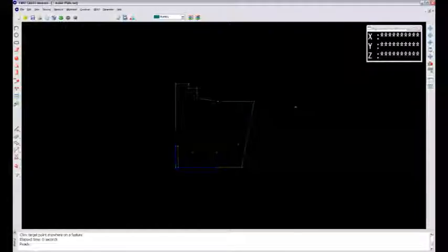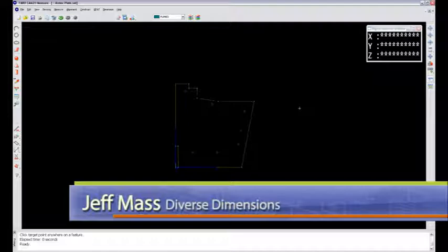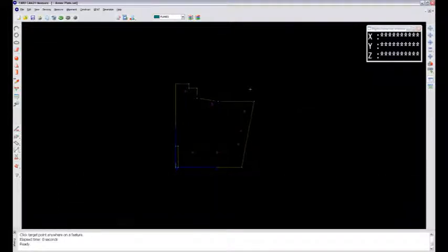Show you guys a trick here with exporting out IGES files. After you've done some feature content or done a measurement session and you need to IGES that file back out so that your people can pull it into their CAD system, whether it be Pro-E or SolidWorks or Unigraphics or any other CAD package for that matter, IGES format for an export usually works pretty great coming out of the Faro system. So we do promote that.